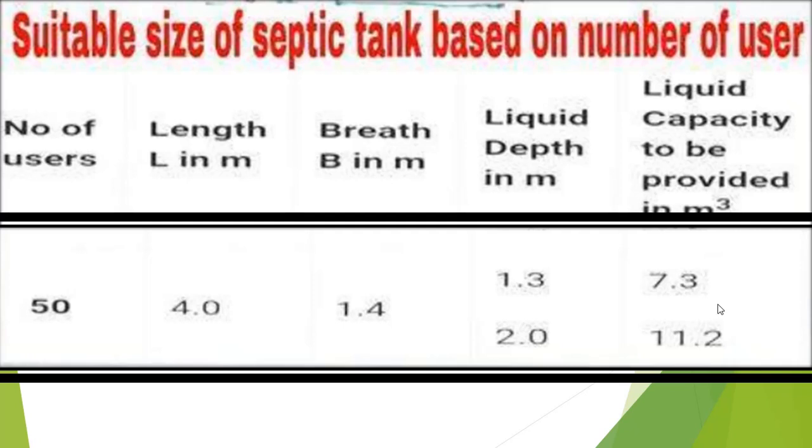A septic tank should have the capacity to store the sewage for long hours, because during that period the sludge decomposes by the biological action of anaerobic bacteria and solid waste settles down at the bottom of the septic tank as sludge. After that, surface water from this tank has to be discharged out, which is known as effluent.